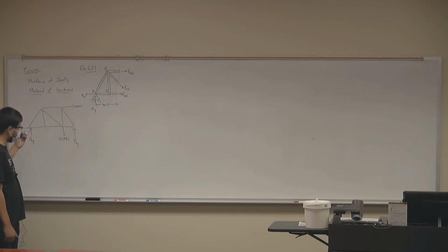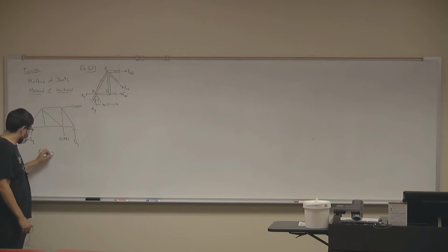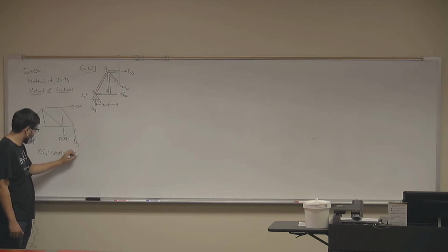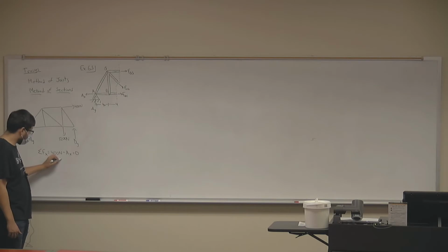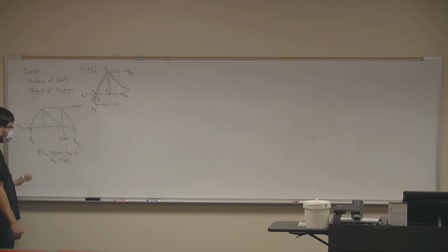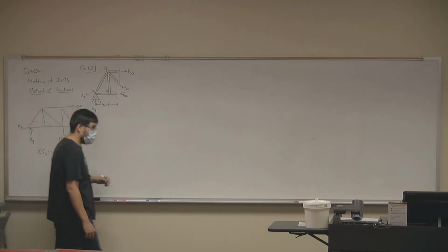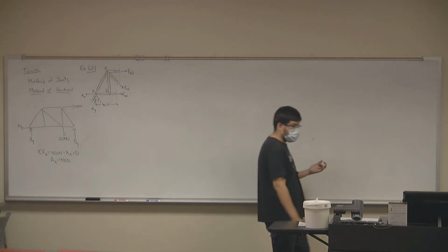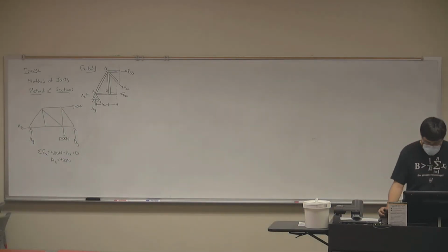AX, right? Okay. So we take our sum of forces in the x direction equals 0. And in the x direction, we have a force of 400 newtons minus a force of AX, and all this equals 0, which means that AX equals how much? 400. There we go. 400 newtons, right? We already drew it negative. Good. And of course, we have to find AY, but we know that AY depends on dy.